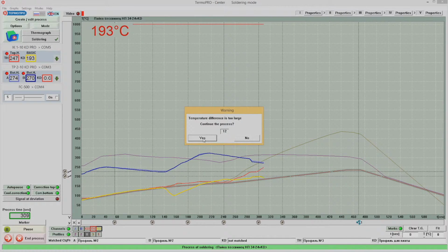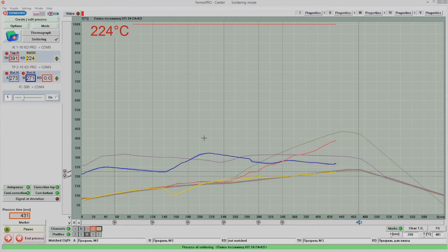The equipment will start maintaining the running temperature at the board, and buttons T+1 and T-1 appear in the left bottom corner of the display. Pressing these, the operator can increase or decrease the current temperature at the component in 1 degree steps. When the required temperature change is achieved, pressing the Continue button will start running the process again, but after the changed temperature value is reached.